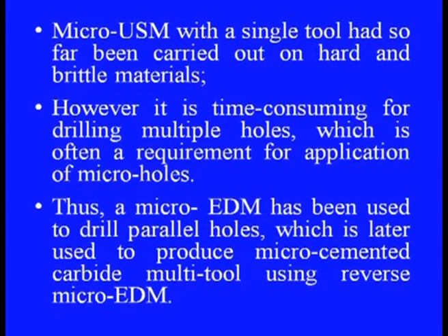However, it is time consuming for drilling multiple holes, which is often a requirement for applications of micro holes. Thus, micro EDM has been used to drill parallel holes, which is later used to produce a micro cemented carbide multi tool using reverse micro EDM. The multi tool was further used in mode 2 micro USM.